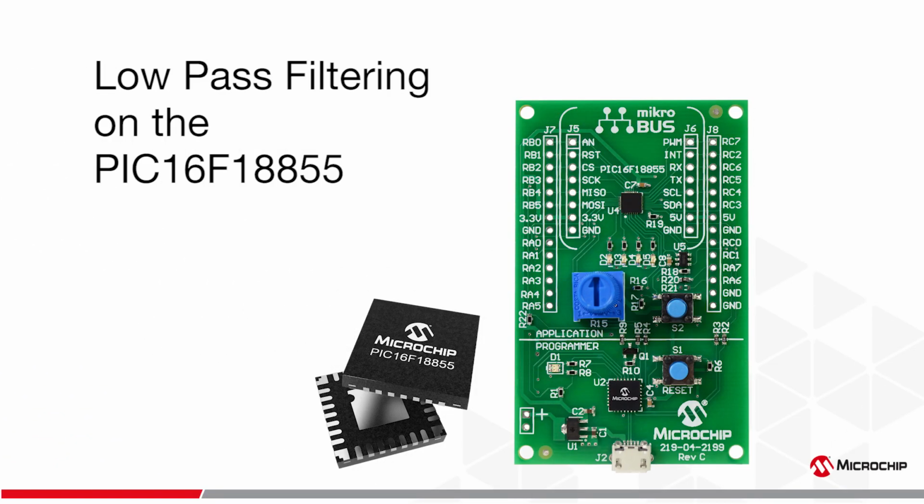This will be a tutorial covering how to use the low-pass filtering capability on the analog-to-digital converter with Computation (ADCC). This peripheral is featured on most newer PIC devices. By the end of this video, you should have a good understanding of how to set up the low-pass filtering capability. Additionally, you will be able to calculate the cutoff frequency of your low-pass filter based on parameters set in MCC. So if doing something like this interests you, please continue watching.